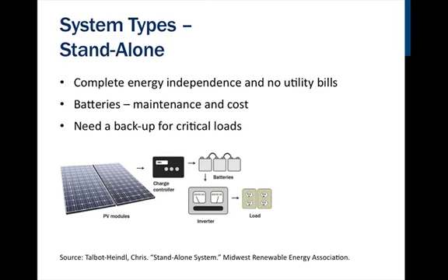With a standalone system, you would have complete energy independence and no utility bills. You would need batteries, which are expensive and do take maintenance. You have to maintain fluid levels and charges, and you periodically have to overcharge the batteries to loosen the lead buildup. The system has a large balance of system footprint since it has so many components.